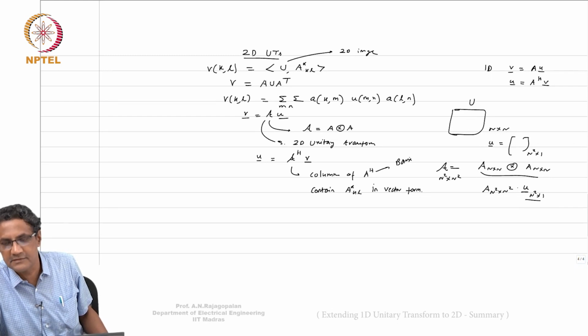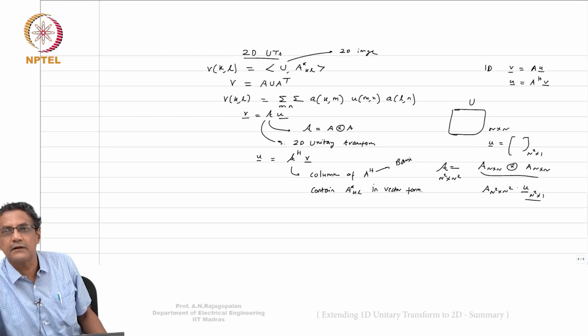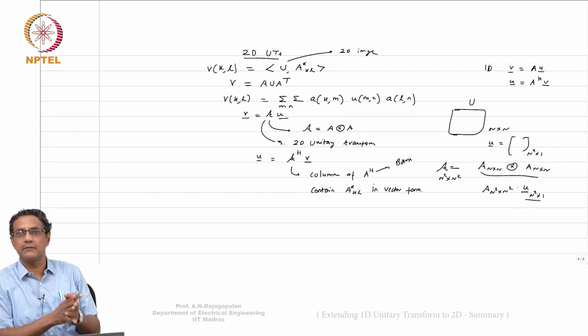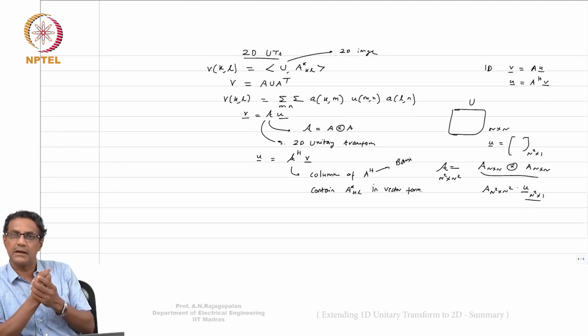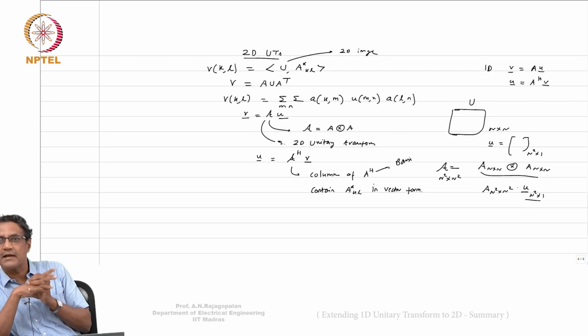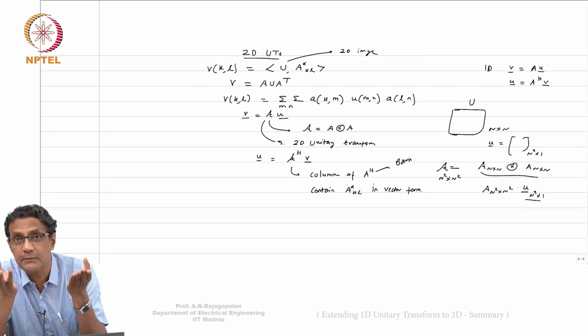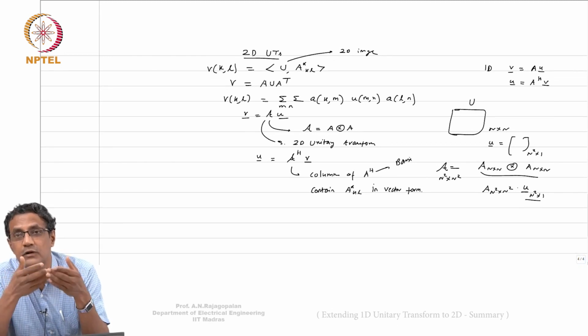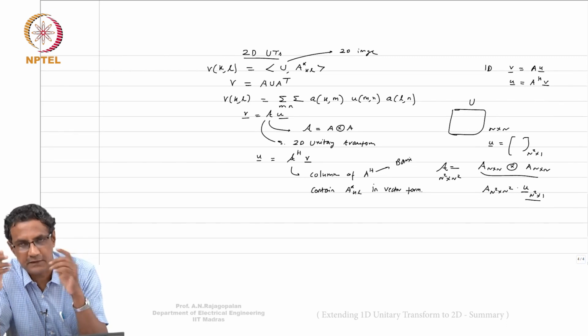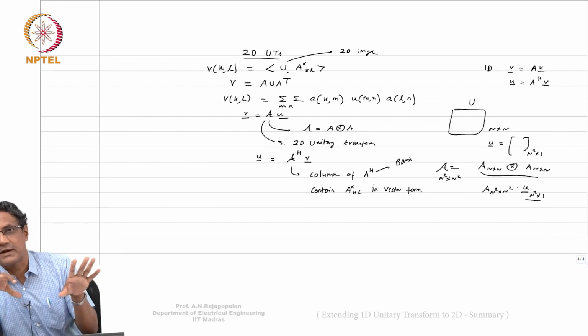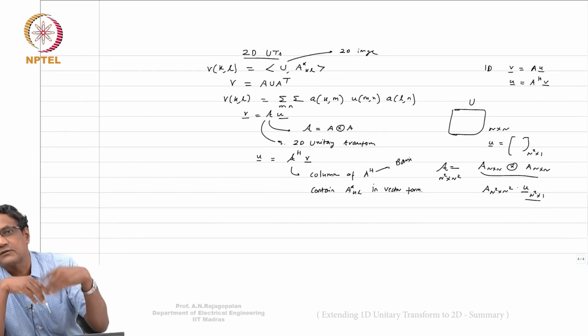You have a complex basis, and then again you can think about a magnitude spectrum, you can think about a phase spectrum, just like you have in 1D. All of that is the same. For an image, what is the interpretation? The interpretation is how does your intensity change with your spatial coordinates? In time, we say how does the signal strength change with time. That is the interpretation of frequency in 1D. In 2D, there is no time notion. There's only x and y.